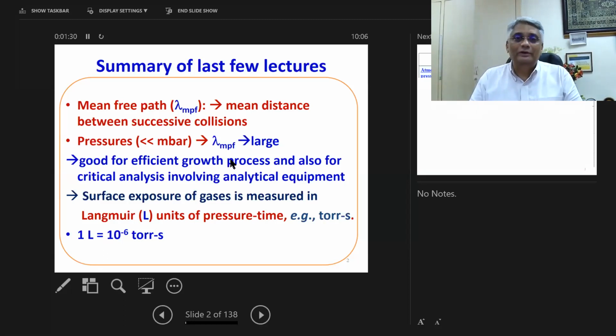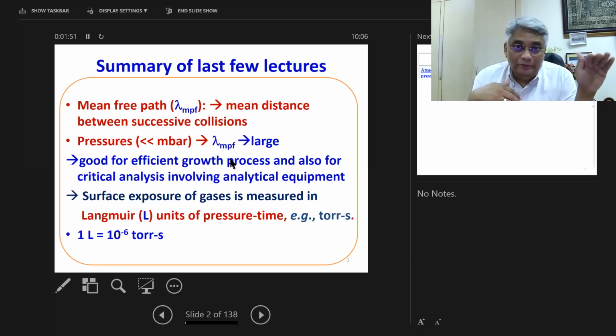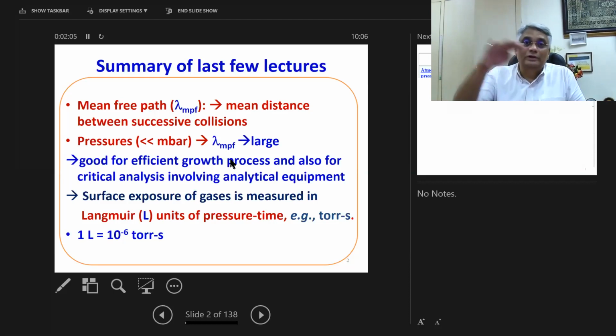So you also have a requirement where I gave an example of titanium nitride or an oxide system. You start with aluminum, you vaporize it. If you have vacuum inside the chamber, no traces of air molecules, no oxygen, then you get a pure aluminum layer. If there is oxygen present inside the chamber, that means you have not evacuated the chamber to the required levels. So this oxygen from the air can react with aluminum atoms and you get an oxide formation of aluminum. It's unwanted. You're not achieving what you want. That's why vacuum level is very important.